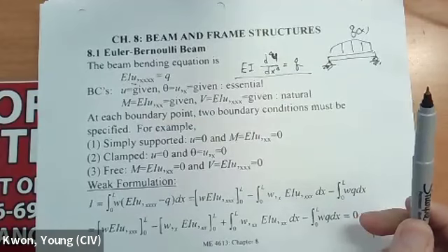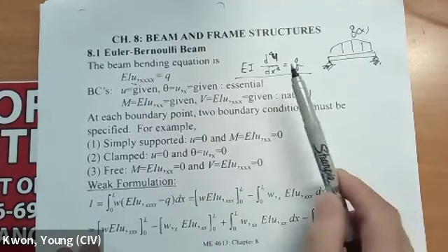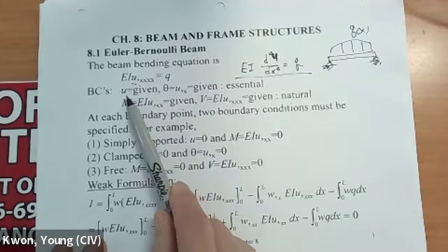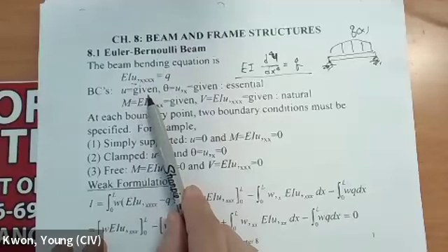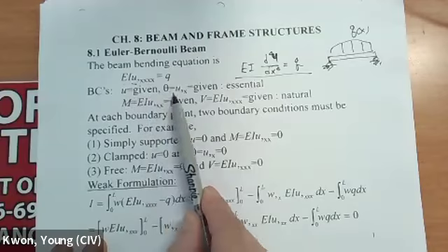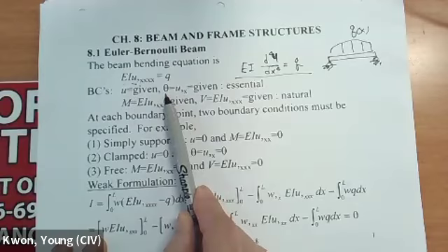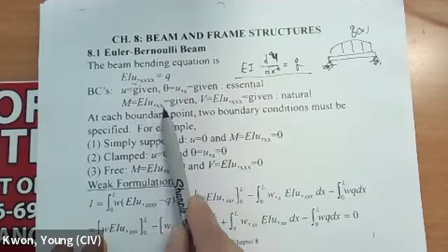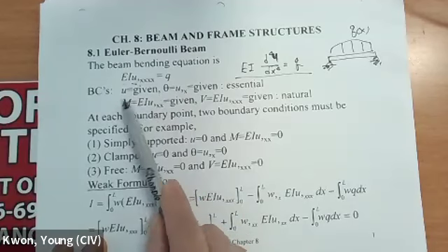So boundary conditions up to the third order, since this is the fourth order. U is the deflection, or transverse displacement, of the beam, and U comma x, du dx, is the slope of the beam, and the second derivative multiplied by EI is going to be a moment.